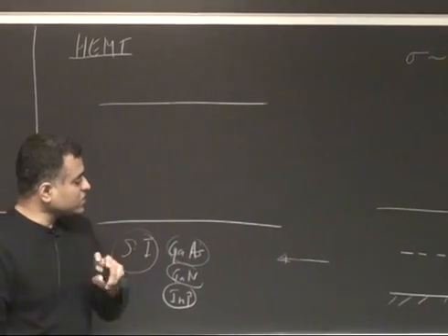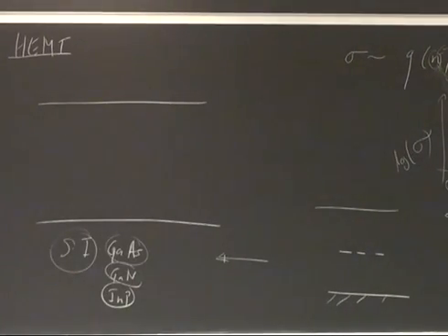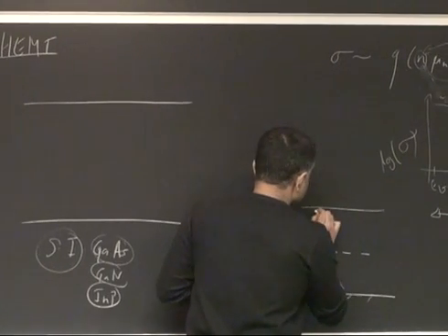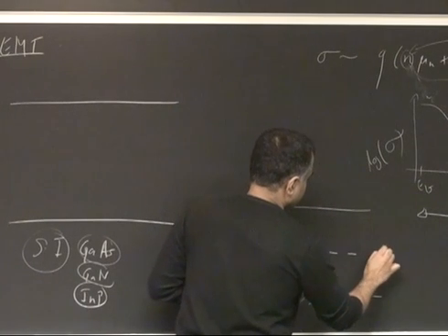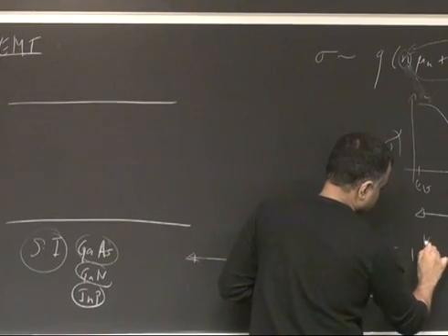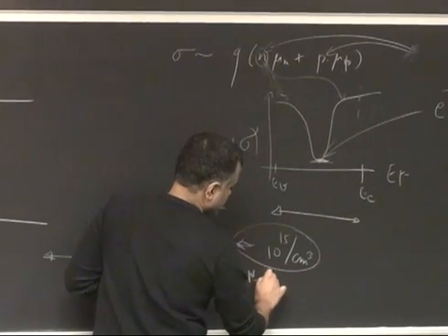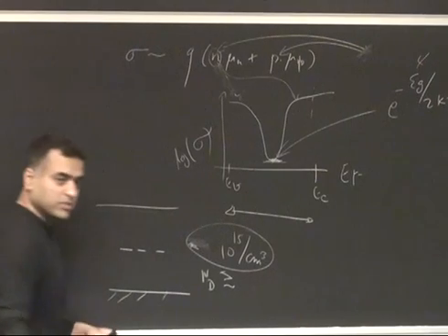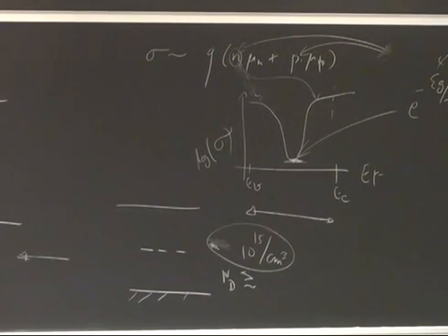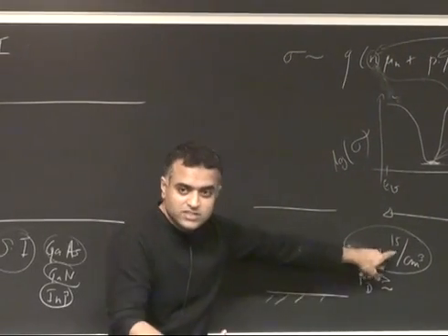And the whole job of those states, and they are mostly what you would call deep levels. For example, if you look at gallium nitride, the unintentional doping is the minimum doping you can get in the cleanest MBE or MOCVD systems, ranging around maybe 10^15 per cm^3, meaning your doping density is always greater than or equal to this much. No matter how hard you try to keep the material pure inside the growth chamber, maybe you can make it better, 10^14 or something like that.